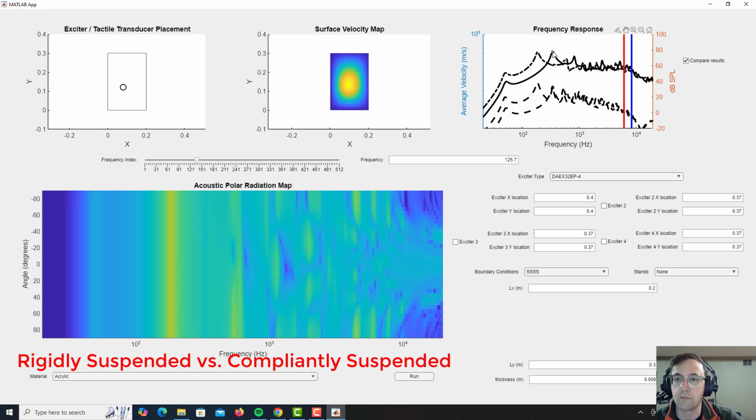So this peak and this peak are the same shape roughly, although in the simply supported or compliantly supported edge termination case, this is broader in space. It's not like such a narrow shape. So yeah, trying to get closer to that simply supported edges will push the resonant frequencies down, which is always helpful. I don't think that either of these moved.